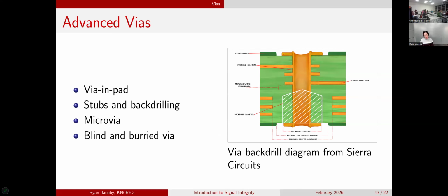And if you've taken EE335, you'll know a quarter wavelength open is going to actually look like a short and cause weird issues. So you can get suckouts at certain frequencies in digital systems. That's going to result in weird distortions and ringing in your digital signals.